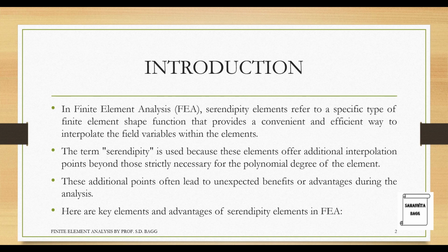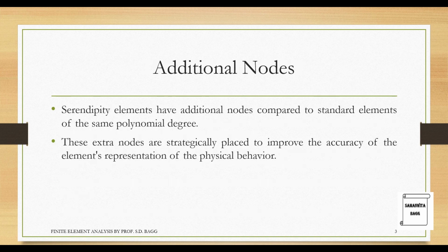Here are key elements and advantages of serendipity elements in FEA. Additional nodes. Serendipity elements have additional nodes compared to standard elements of the same polynomial degree. These extra nodes are strategically placed to improve the accuracy of the element's representation of the physical behavior.